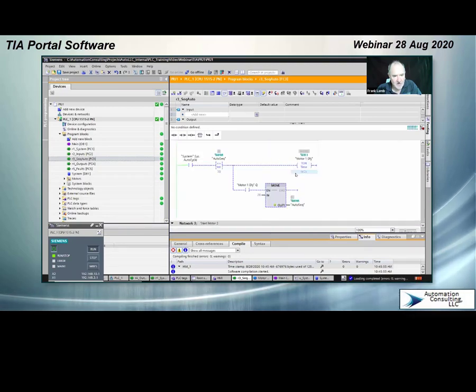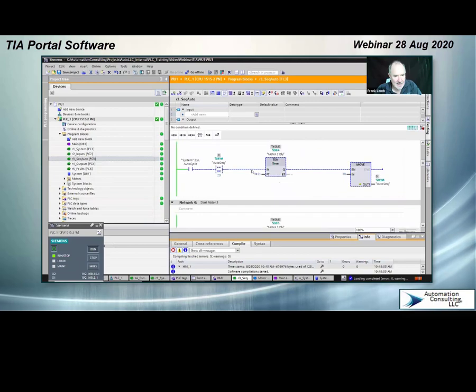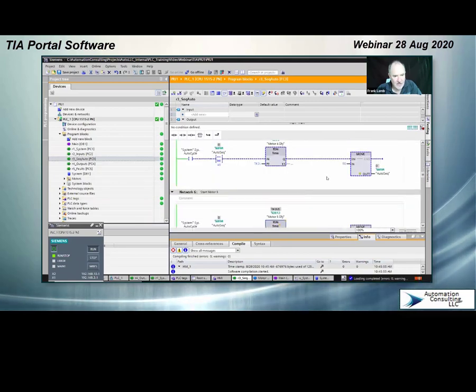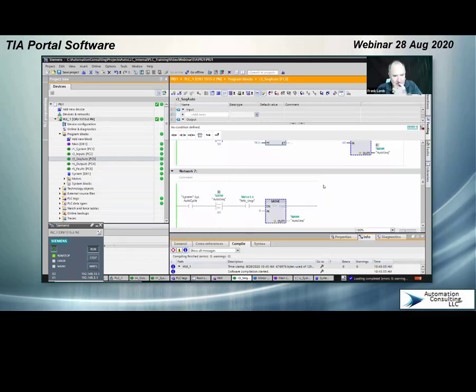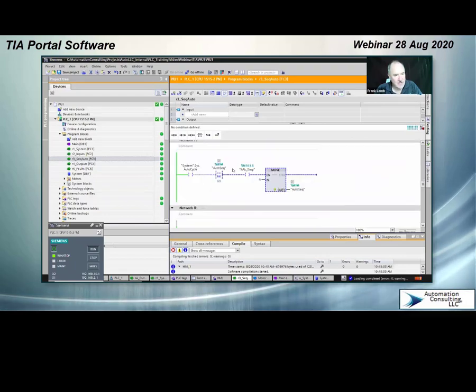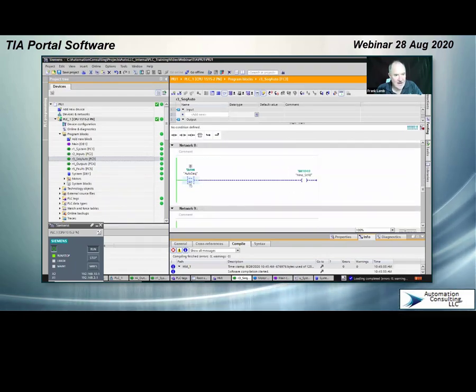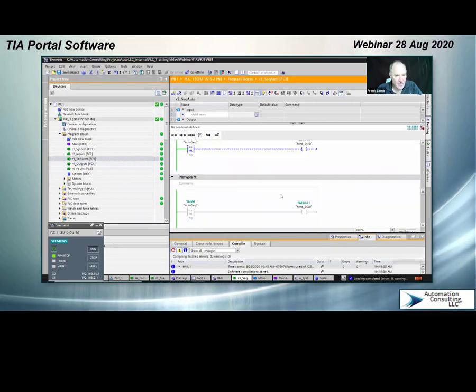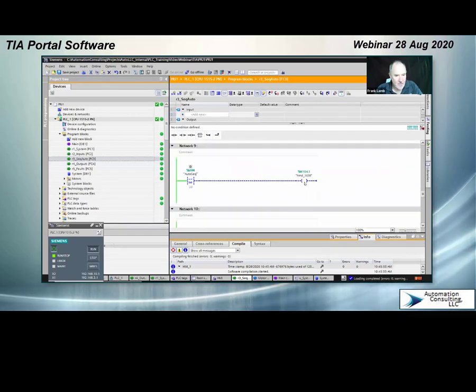So you can see here, I used a different technique. Here I use the done bit like you would do in Allen-Bradley, and here I just pinned it directly to the Q bit, 30, 40, 50, and so on. If you're in step 60 and you press the stop push button, you will go back to 0. So that's the idea behind that. Then all those indicators that drove the motors are right here. In step 20, I turn on HMI step 20, which drives the output.